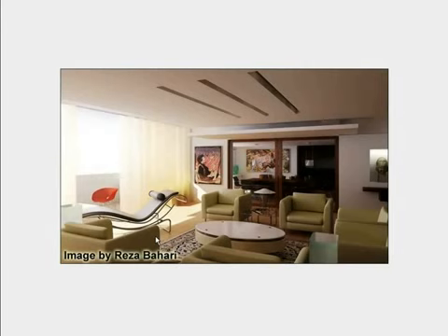In this final image, this is a great example of when you would want to use adaptive subdivision. And this is because there are many areas of large flat smooth surfaces such as the ceiling and the furniture. And even where there's detail needed, such as the paintings, it's really not in an area of the scene where detail is really critical. If it's not shown in the painting, it's not going to be detrimental to the scene.